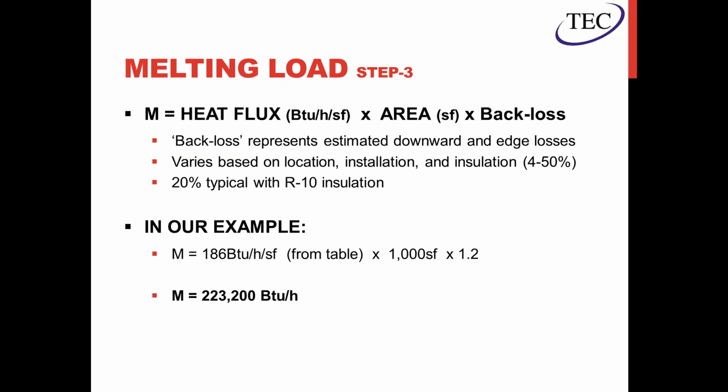So for this example, 1,000 square feet and our heat flux that we've taken from the table and the back loss safety factor, our melting load is just over 200 MBH.